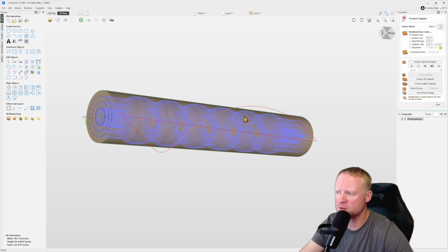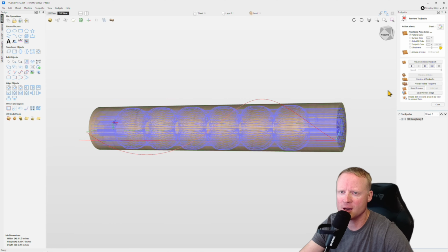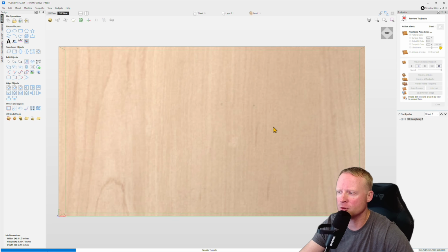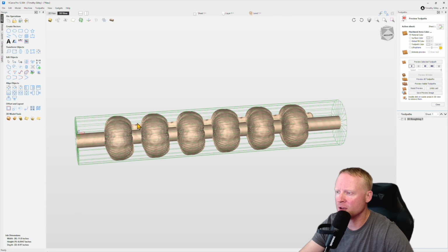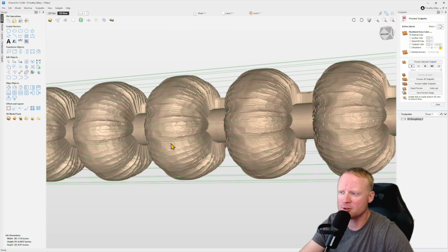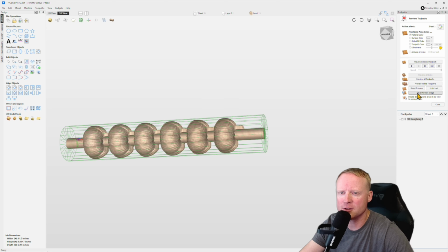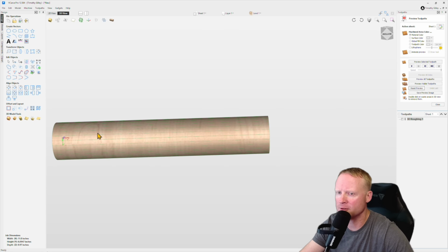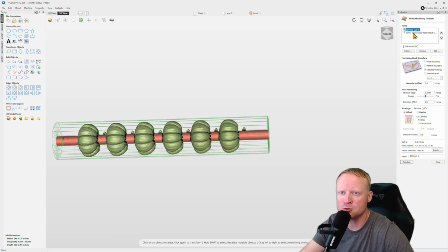And so here's what it's projecting our roughing toolpath is going to look like, which looks pretty good right off the bat. We have a pane over here where we can preview these selected toolpaths. So for the roughing, this is what it might look like. And so you can see it's carving the stems out there, which eventually that's going to be cut off. But this actually looks pretty good for a roughing pass. So we'll go ahead and close that. You want to go back in here and reset your preview to make sure that we get our view like we want it right there. And then we're going to come out here and create a 3D finishing toolpath.